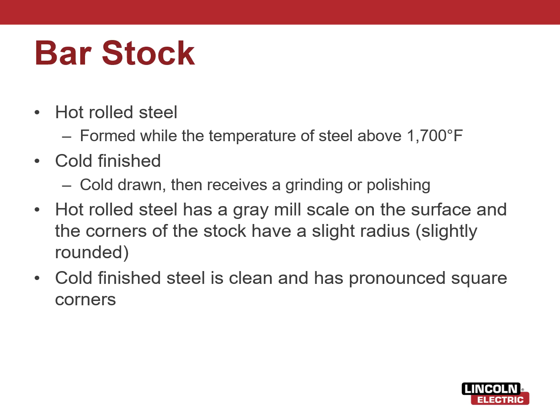Cold finish, or cold rolled, receives a special grinding or polishing afterwards to remove that mill scale. So you're getting bare material. Usually they spray an oil or a film on it, unless otherwise specified, to keep it from flash rusting in transportation. But it comes with the mill scale already removed.